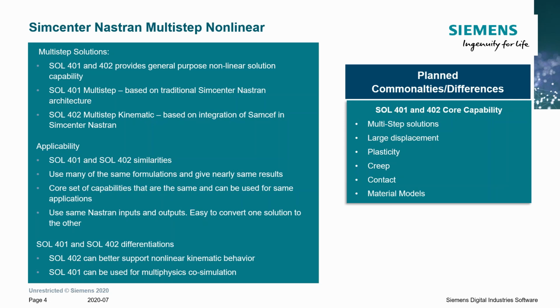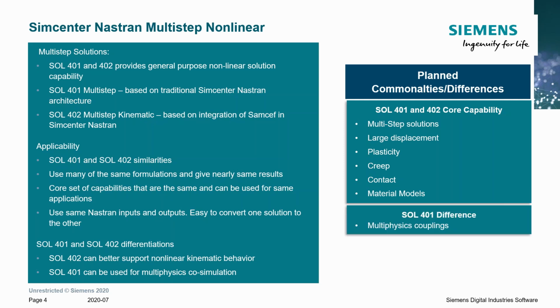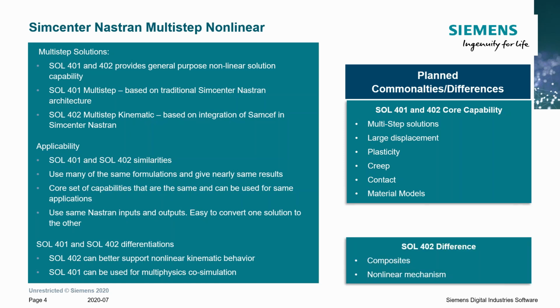So there are planned commonalities and differences. Large displacement is supported in both, although 402 is better suited for that. Plasticity, creep, contact, and material models. And again, I'll go through more detail on that a little bit later. And then 401 has the multi-physics couplings, and 402 is a little more robust in composites and in the nonlinear mechanisms.